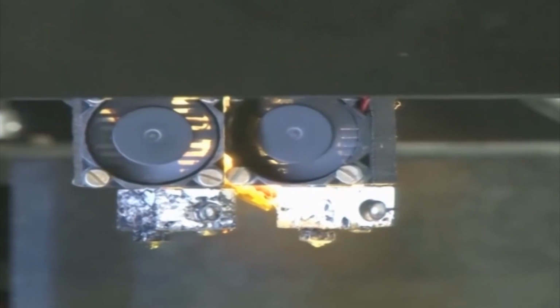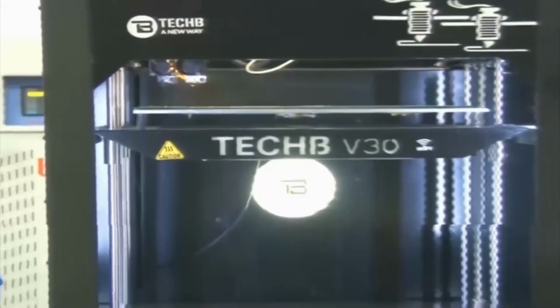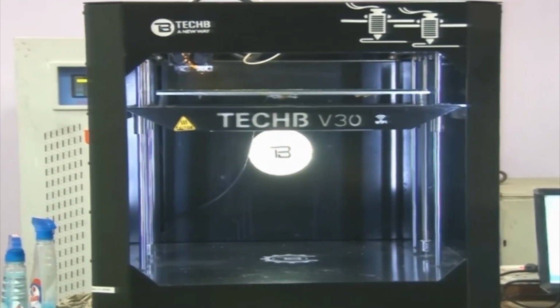This is one more thing that we mentioned earlier, there are two fans, fan 1 and fan 2 here. After the material fuses it becomes viscous, and for a long time it will de-shape the CAD model if it is not properly controlled with respect to temperature. So, after depositing, these fans are responsible for the cooling and solidification of the layers. That is why it is mentioned in the software as cooling.